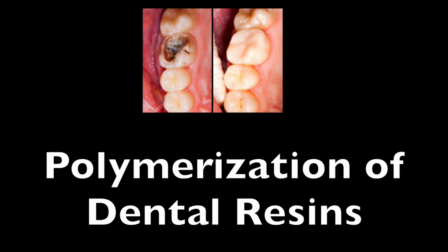What happens is, as the polymerization progresses and the resin transitions from a liquid to a more viscous gel, the movement of those growing polymer chains becomes restricted. So they're kind of getting crowded. They're getting crowded, yeah, they're bumping into each other. And so it makes it harder for them to find each other and terminate the reaction. Oh, so they can't escape.